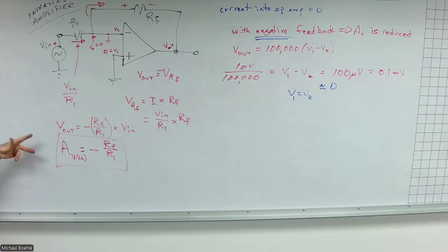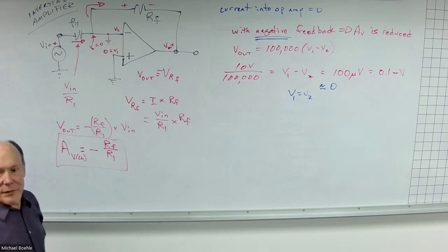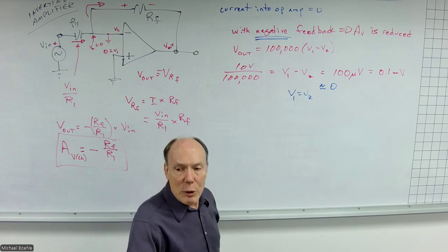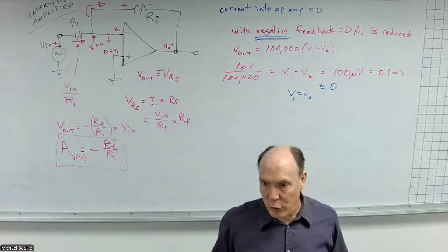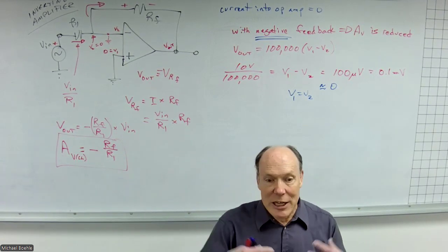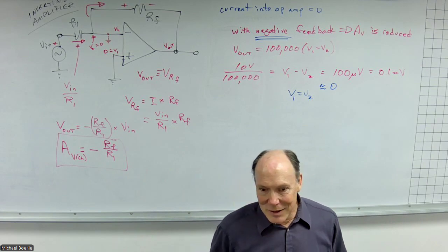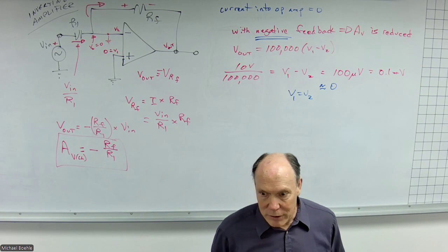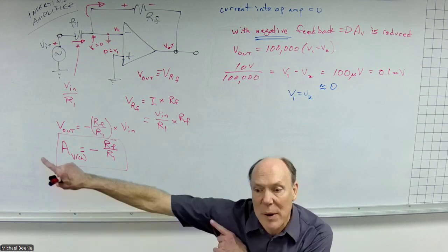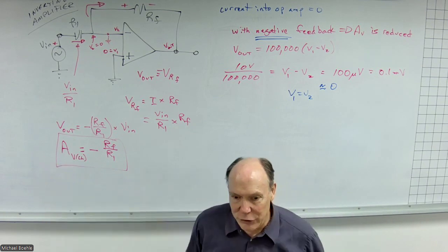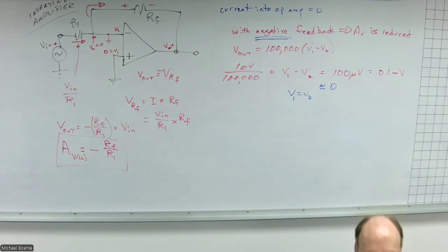And that voltage gain is set by two physical resistors that you put in. No more r'e to deal with, right? Very linear response because they're resistors, they don't change. So you're not going to have any distortion from too high of a gain, or too high of a signal, other than what we've already talked about. There's a power bandwidth that we have to calculate.